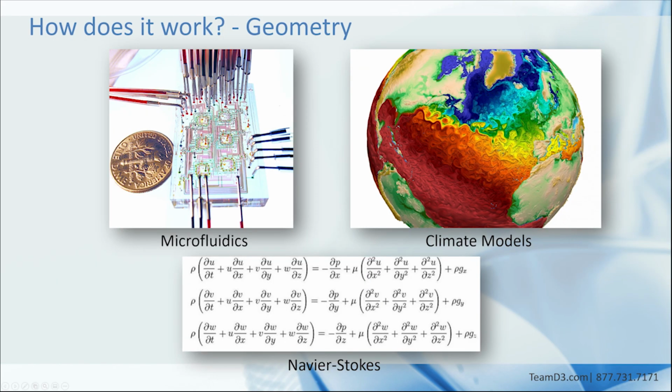There are scale limits, of course, and it comes down to the equations that are employed by the software in its models. Autodesk CFD uses the Navier-Stokes equations, a common choice for general-purpose solvers. The physics that can be represented using Navier-Stokes cover a wide range of physical scales, but at some point models can get too small or too large. The dominant physical effects just aren't accounted for. Turbulence and boundary layers in microfluidic applications would not be well represented by Navier-Stokes.